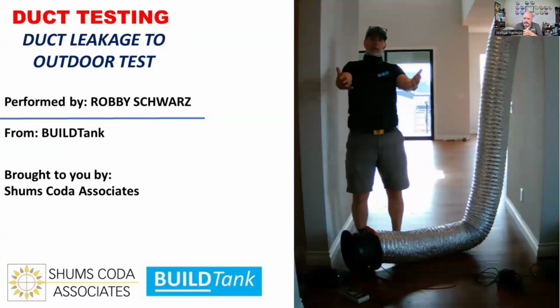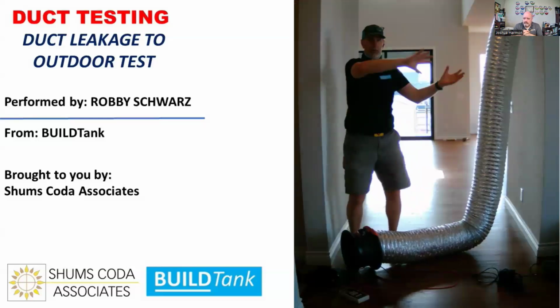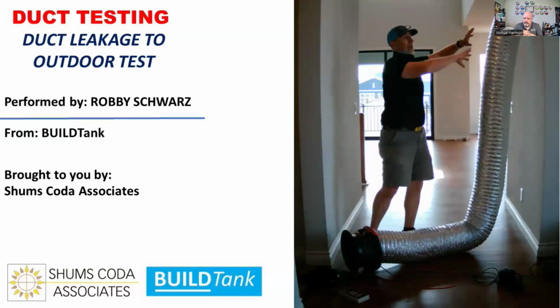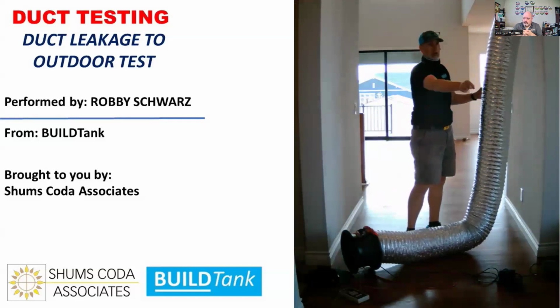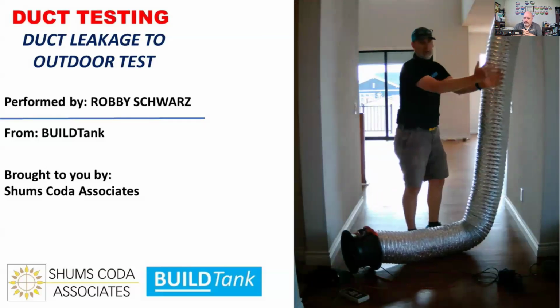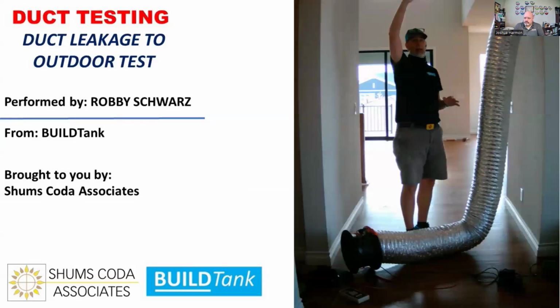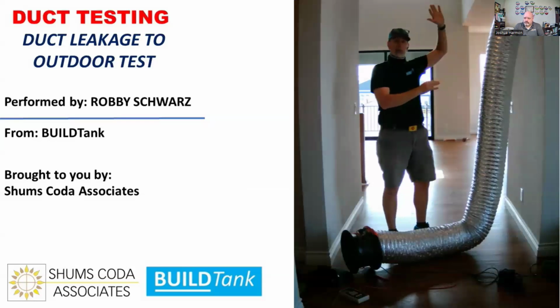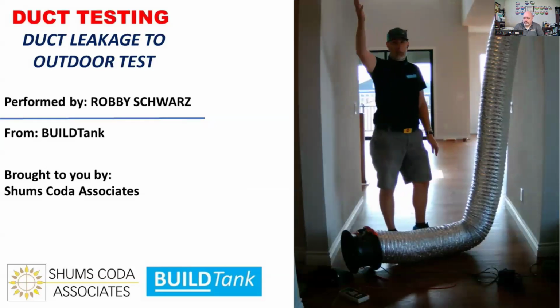Okay, so we have pressurized the house using the blower door. We've opened up the fan opening of the duct tester, so air is going into the duct system and air is in the house. So if I have a hole in this piece of duct here, air would not be going across that hole because the pressure inside the duct and the pressure outside the duct are the same. So you need two things for air to move through a hole. You need the actual hole, and you need a pressure difference across that hole for air to move. But up in the attic, if I have duct up in the attic, the pressure outside the duct is not the same, so the air being pushed through here would be leaking outside, and that's what I'm going to be